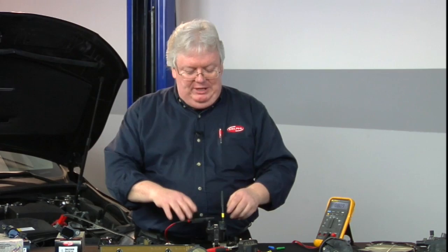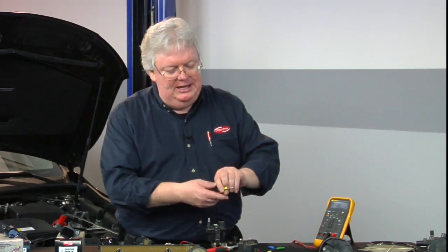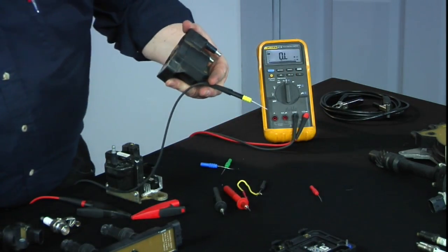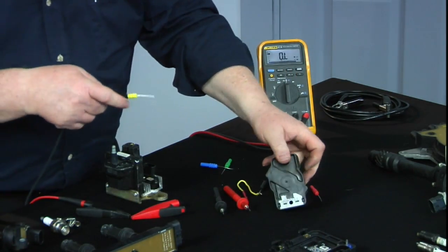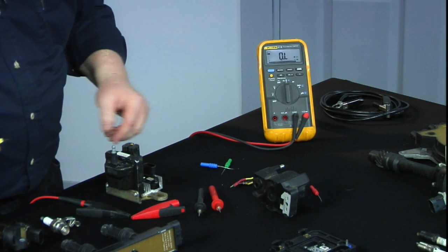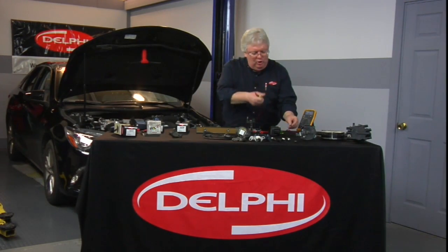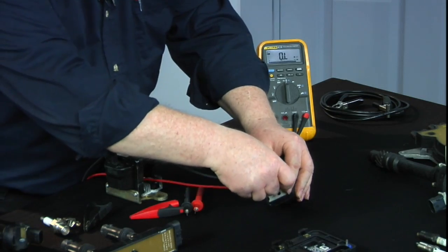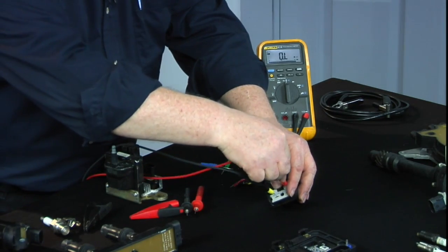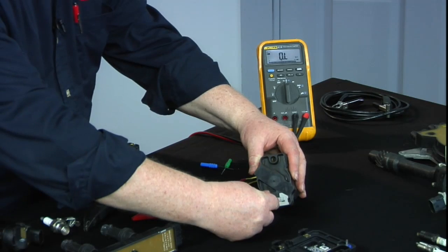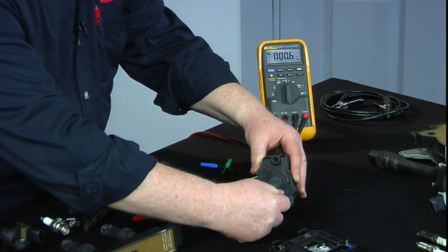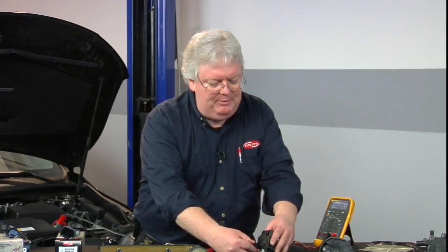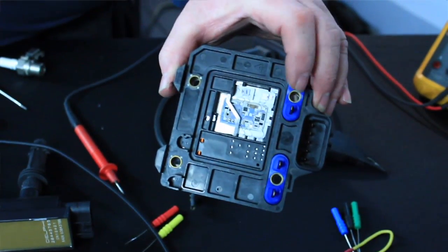Now these tests, we can fast forward to DIS. Same thing. They were pretty cut and dry. We're going to see it's not so cut and dry with Coil-On-Plug here in about 60 seconds. So now we can do the same testing here. Get my probes, go into the primary, and the DIS was really cut and dry. You can measure the primary like we're doing here, and we've got 0.6 once again, so about 20 amps is going to flow when that primary is turned on by the ignition module.